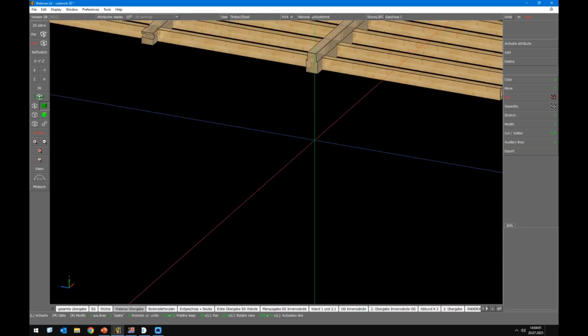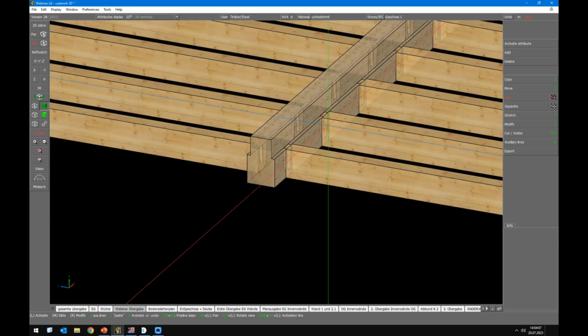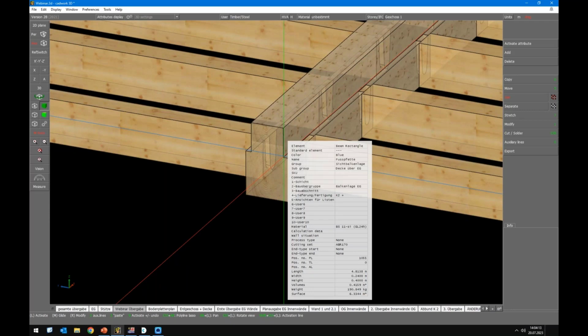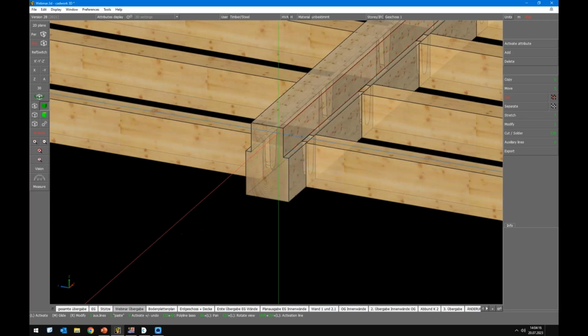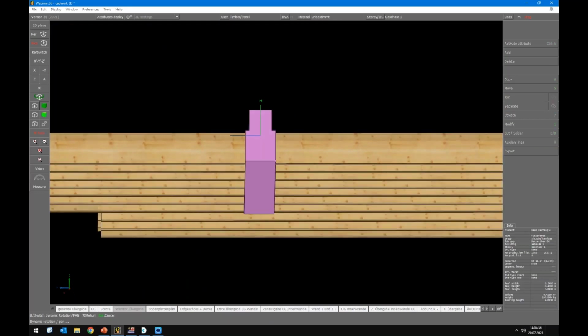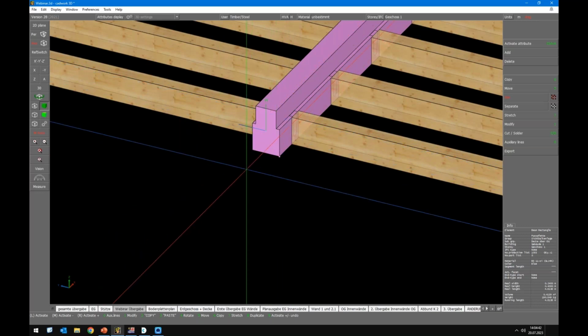So the ceiling beams are connected via dovetail connection, and the bearing beam will be a bit inside the ceiling structure. Otherwise, we would get too little stiffness, and it was decided to lift this a bit up. Maybe not so good for acoustic reasons, but the building constructor decided to have it bottom to bottom for floor and bearing beam here, or for this downstand beam or flush beam, however you call it.